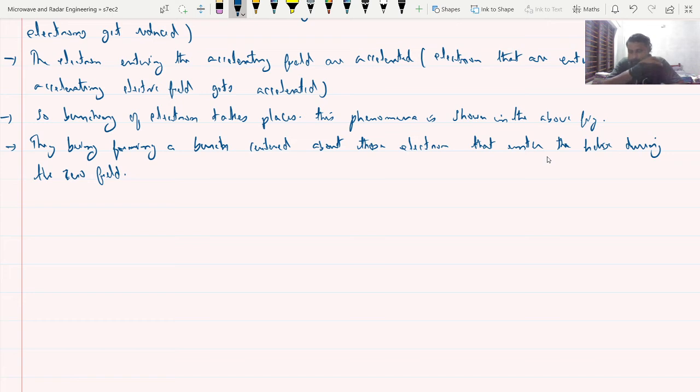as the electron propagates more. As the electron is being propagated inside the slow wave structure, more interaction will be taking place between the electron and the electric field. So bunching becomes more compact at the end of the helix. That is what takes place in the traveling wave tube. So I will write that one.